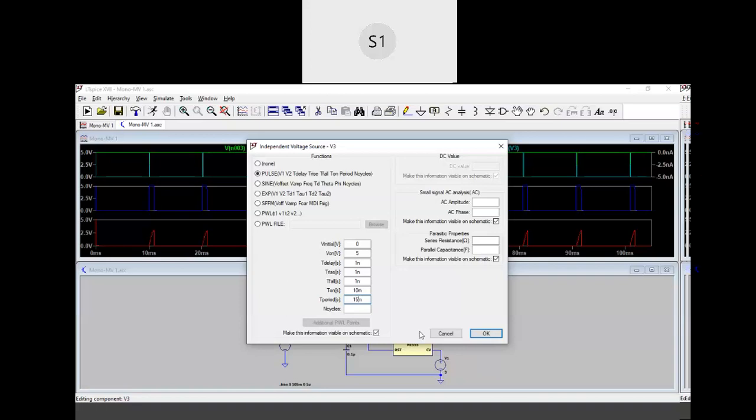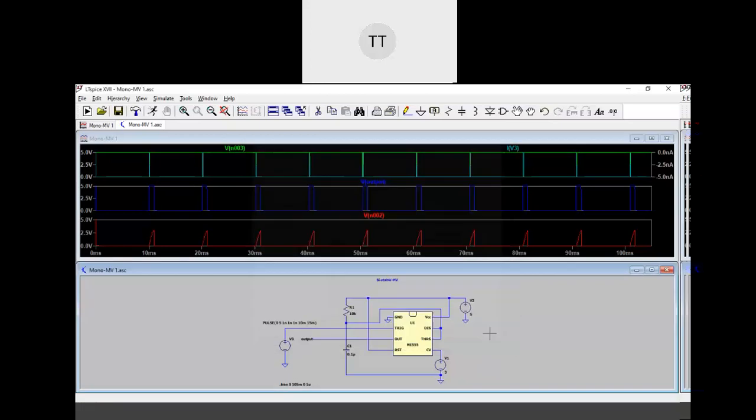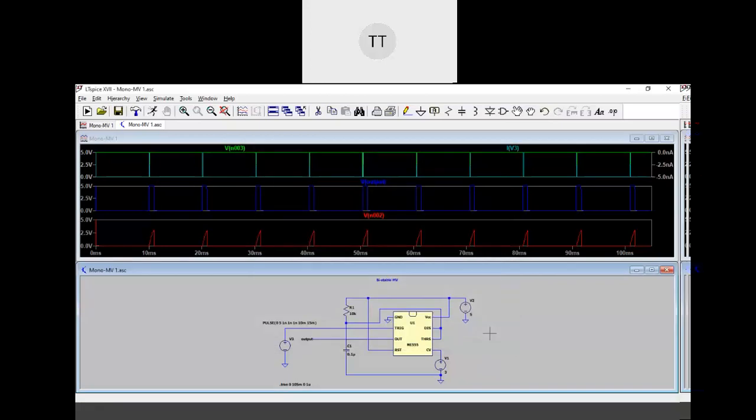The trigger signal, that is the input signal, is less than VTL for around 5 milliseconds. Correct? Let us see what happens. What is the expected pulse width now, as per this? It should be 916 microseconds. Correct? Shall we run it now?